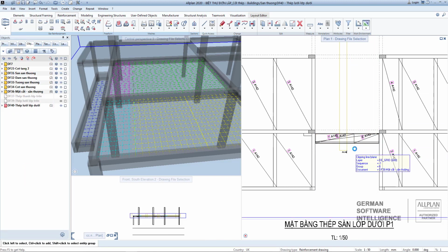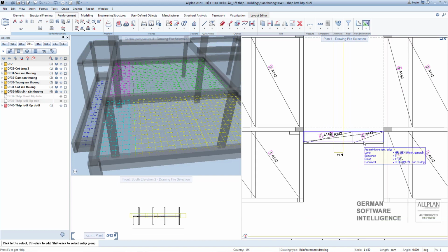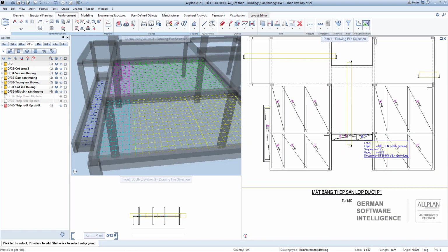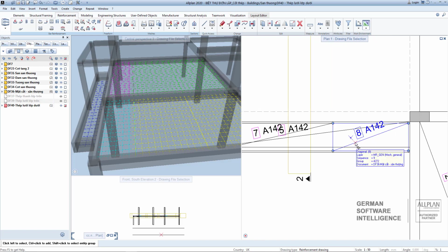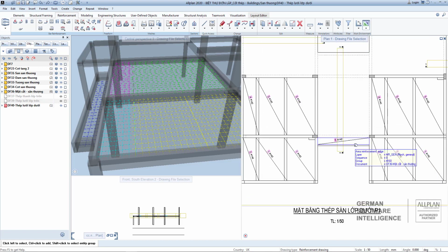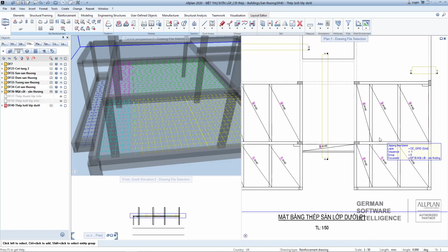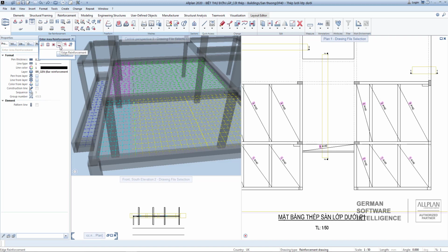However, because of the structural characteristics of each slab, you cannot place meshes through beams as it will collide with rebar in beams. So here, I will delete the edge mesh and replace it by the method of placing rebars straight. You will use the draw bar tool for edge and support as in the previous lesson.